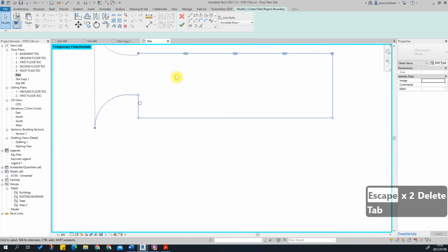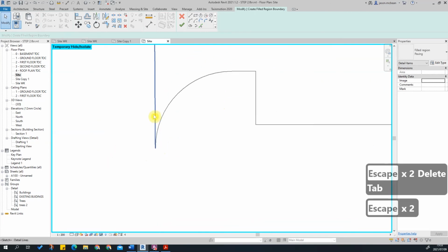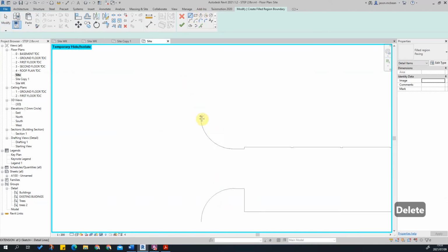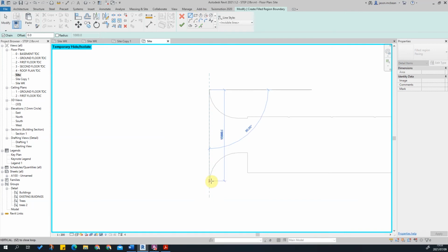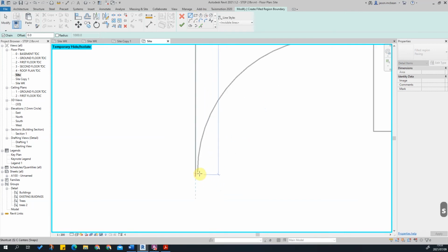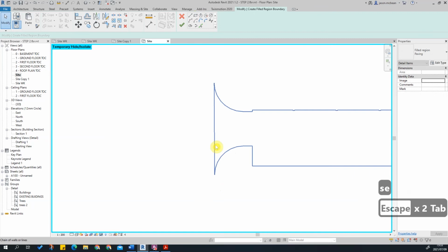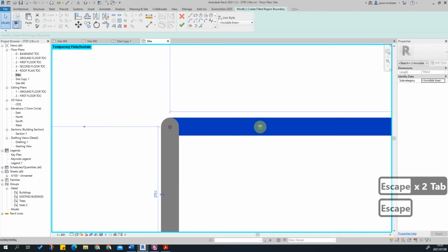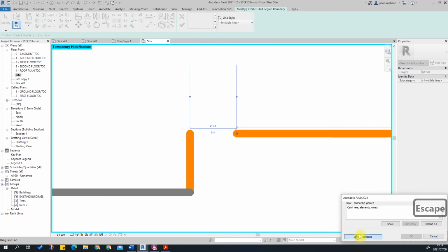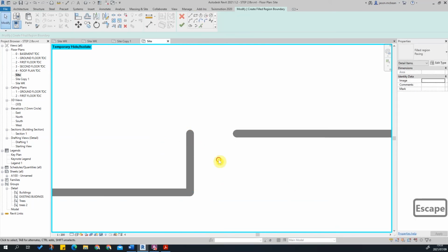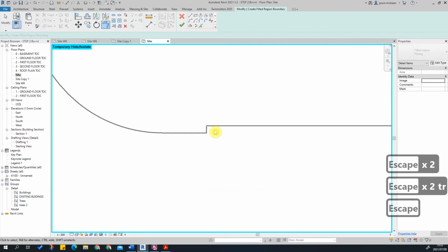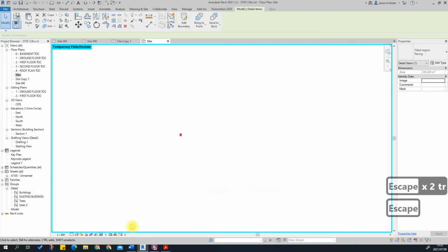Okay, now tab. Here's a hole here. So this is not working. Get rid of that. Let's draw a line. That usually solves the problem from the end point. Snap end. Force it to snap to the end. Try that again. Perfect. We still got a hole here. So something is not working here. Unjoin elements. Sometimes there's two bits of line work. If you hover and you see here, it'll tell you one. Let's see here maybe. One. Okay. Trim. There we go. Now that's worked fine.